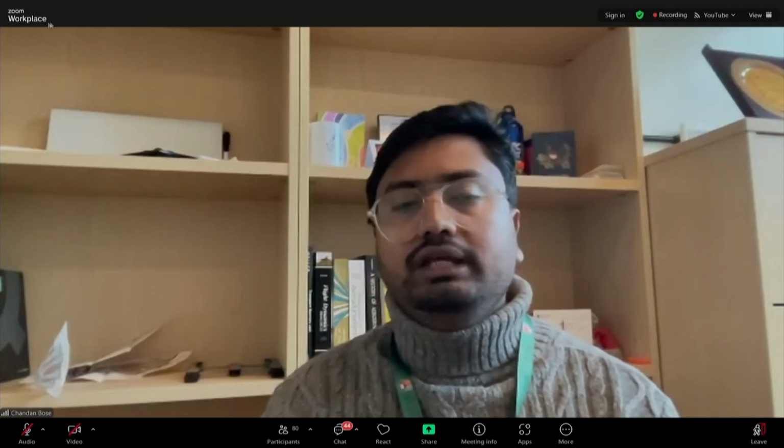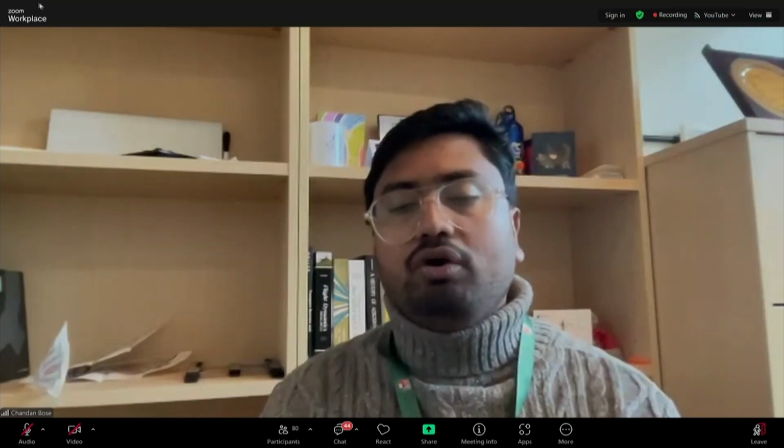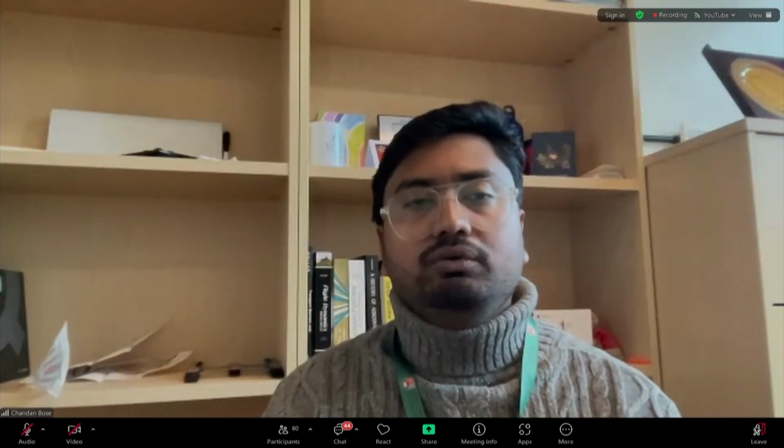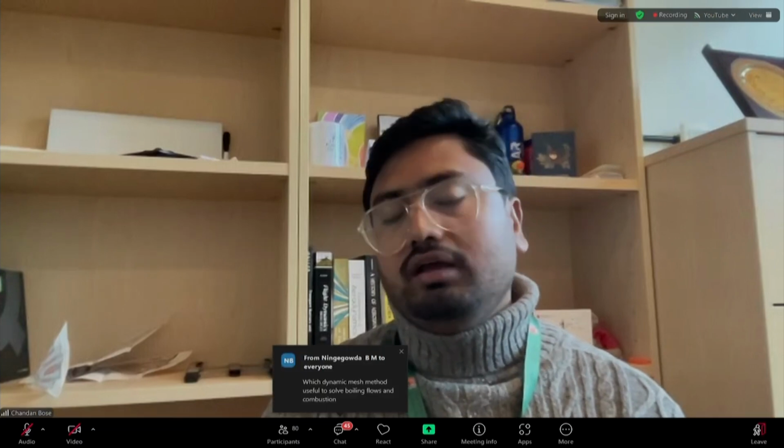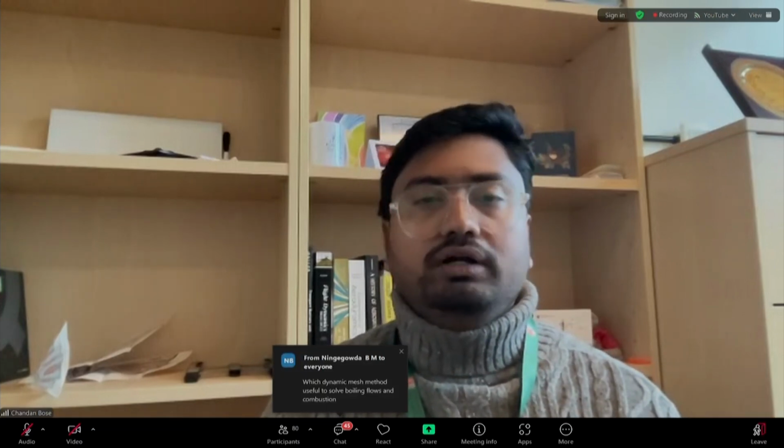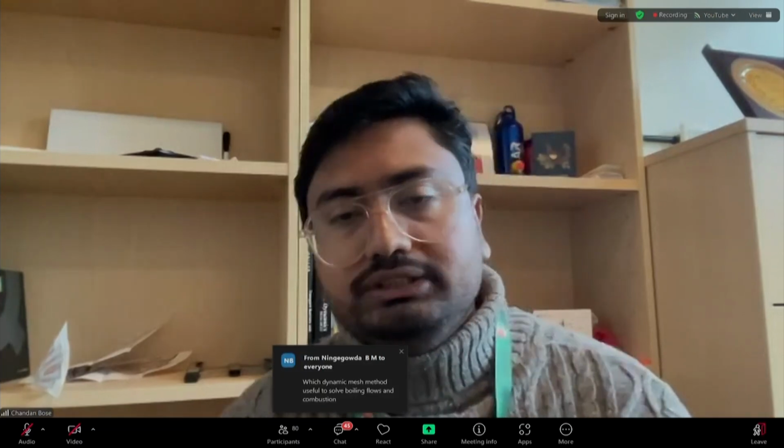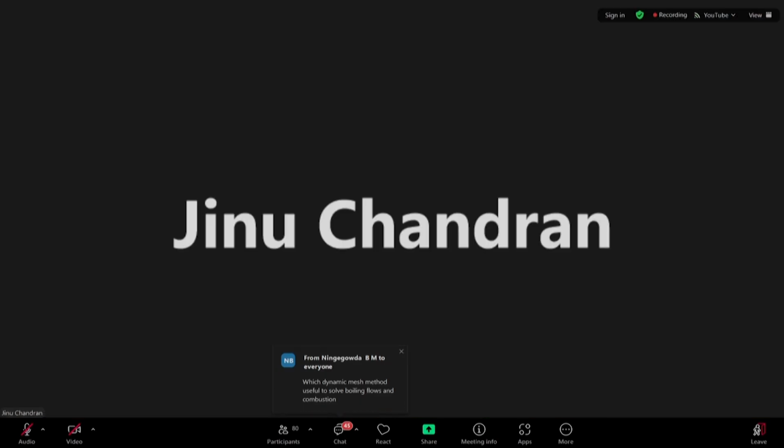For example, maintaining the Y plus distance or the first cell distance over the body. And this becomes important if you want to capture a very turbulent flow, right? And you want to resolve the flow to very small scales. In those cases, Snappy Hex Mesh might not be the best option. So you might want to use a more sophisticated mesh. So what is the next available option?